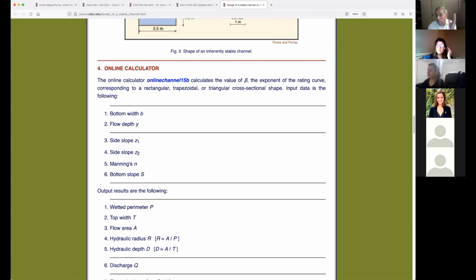First of all, you know the discharge. The discharge has to be given to you. Any design of any channel would need a discharge. And the discharge comes from the hydrology. People have asked me when I used to teach, what's the difference between hydrology and hydraulics? And I said it's fairly simple. The hydrology will determine the Q's, and the hydraulics will determine the Y's, the stages, the pressures, to design the structure. Hydrology does not get involved in the actual design. Hydrology is prep. You're preparing, figuring out what the Q is, and the Q comes from the hydrology, from the rainfall.